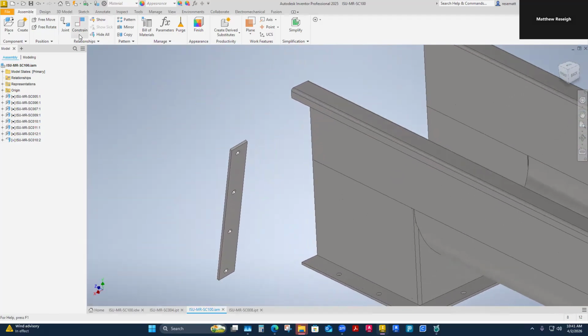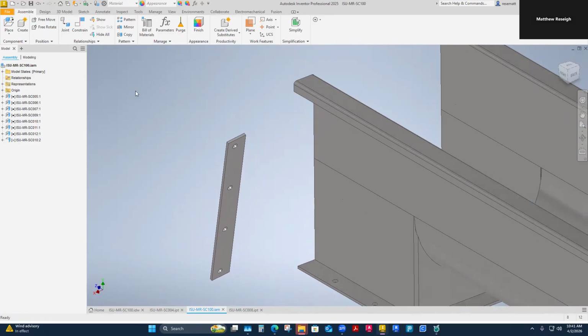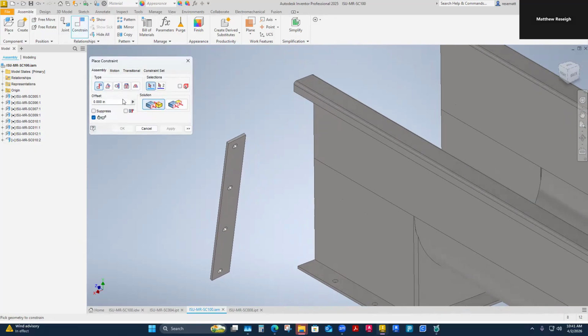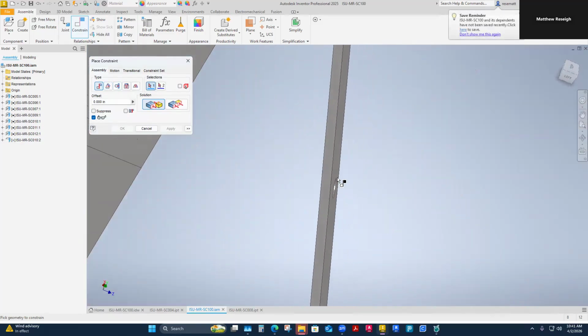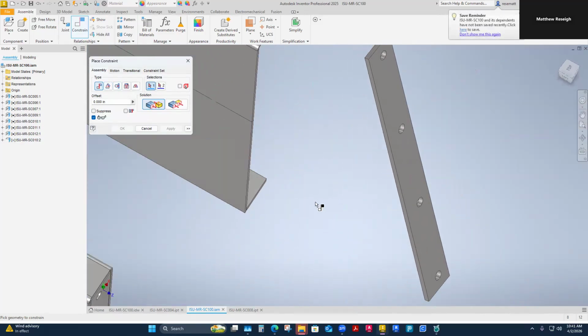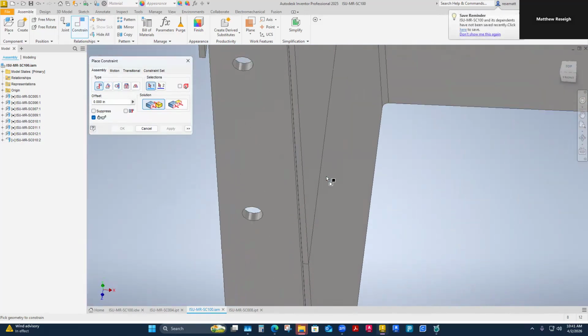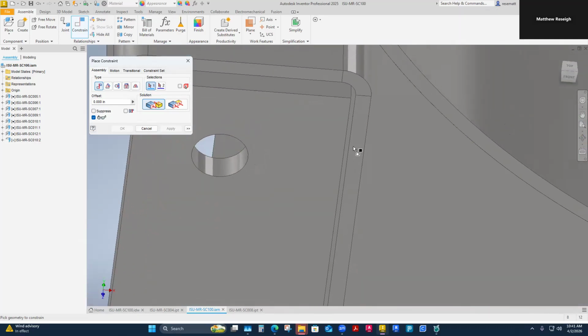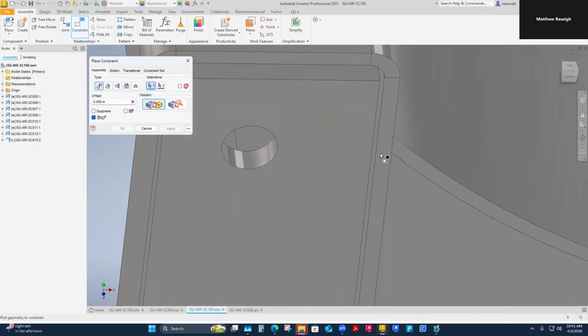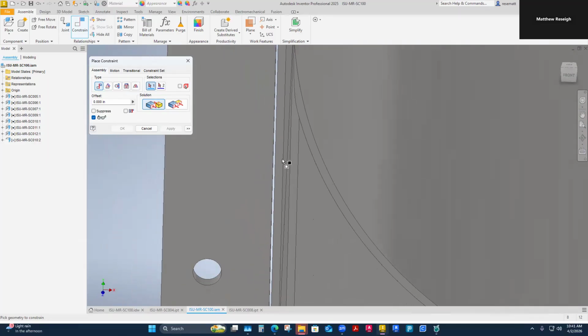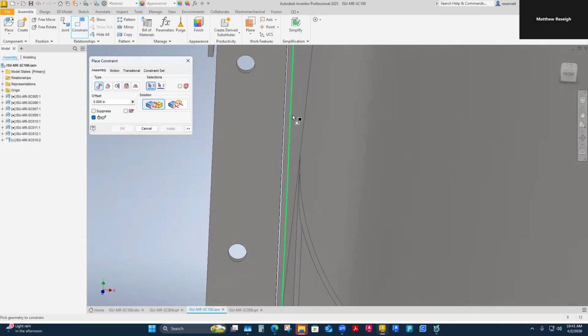And then I'm going to do my normal constraints that I would do in an assembly that we've done before. So I'm going to go to my constraint tab and say, well, I know that this piece goes up against that piece, but it's actually got a 30 thousandths clearance. That was just so it slips over pretty easy, and it kind of matched the clearance that I was creating.